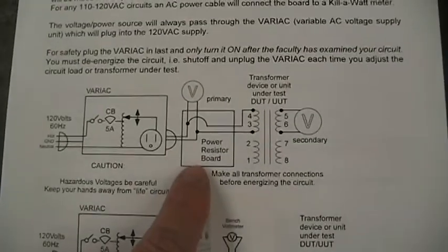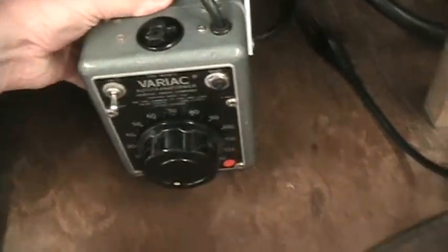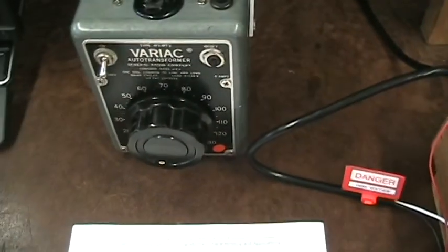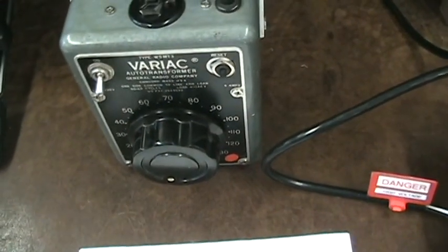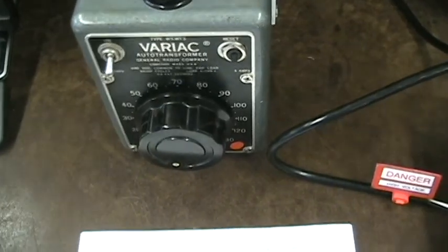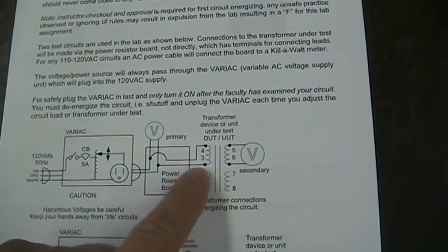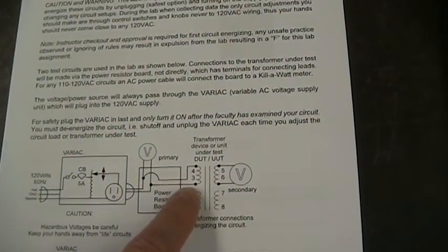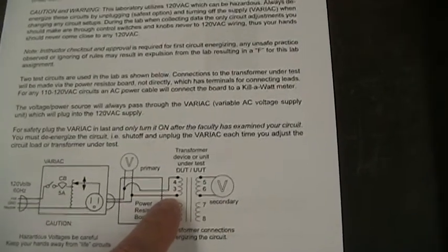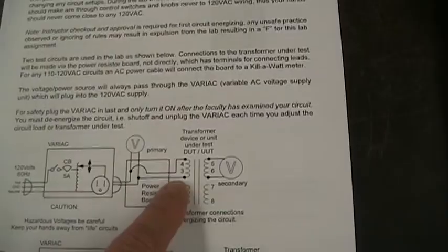For the active measurements, we're going to connect a voltmeter, adjust the variac, and then take measurements across the full range of the winding voltages. This primary winding is rated 115. We'll go from 10 volts to a maximum value, recording every 10 volts. So I'll record that data and then you're going to analyze it.